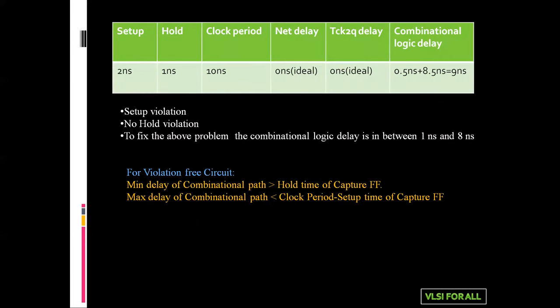From the above discussion, I have concluded that the minimum combinational logic delay must be greater than the hold time of the capture flip-flop. And the maximum delay of the combinational path is less than the clock period minus setup time. So from the previous discussion, we have made these calculations.